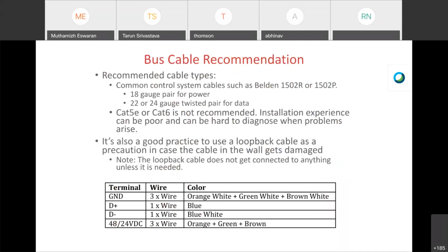Okay, in case I have a project running Cat 6 with a very small number of keypads, because it is very easy to tell an electrician to pull a Cat 6 cable, whereas if I say a 4-core cable with this specification, they'll ask what the cable is, and you need to give them the cable. If it is already being run by them, you can actually connect via Cat 6 also, but use this configuration: 3 pairs for power and just a pair for data communication.